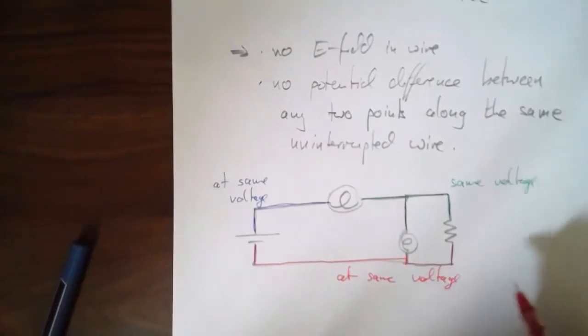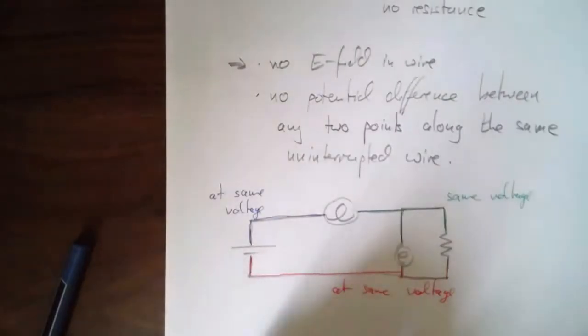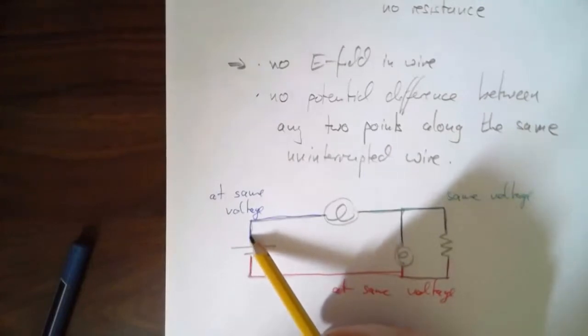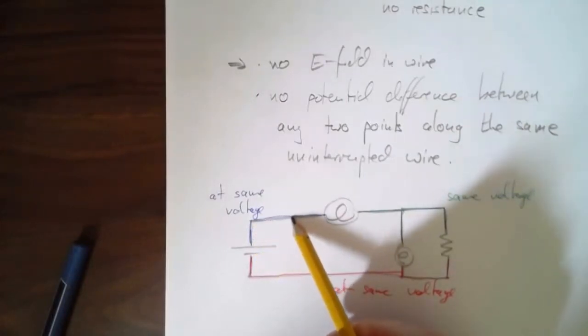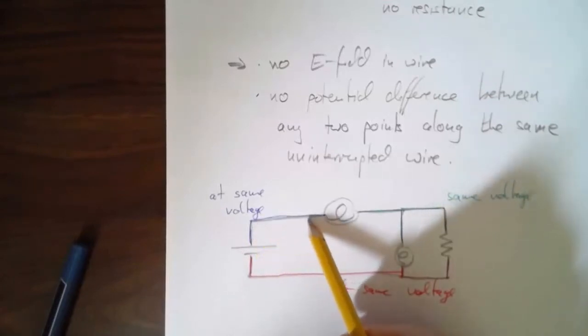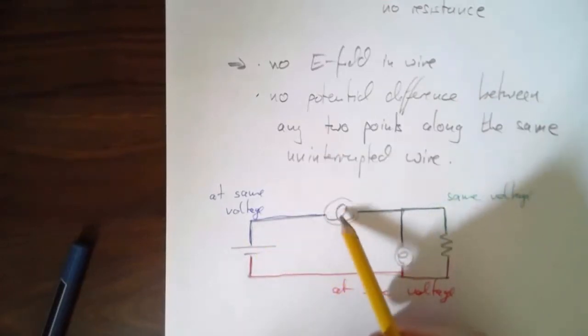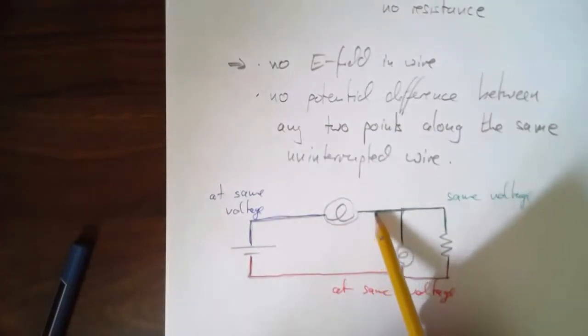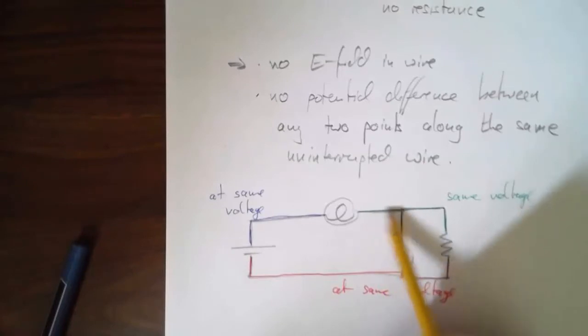Realistically, because wires have a small resistance, there will be a very gradual change. There will be a very small, very gentle downhill path. Downhill meaning lowering the voltage as we go, ever so slightly. The big chunk of it would still be in the light bulb or the resistors. But then here again, it won't be perfectly flat.